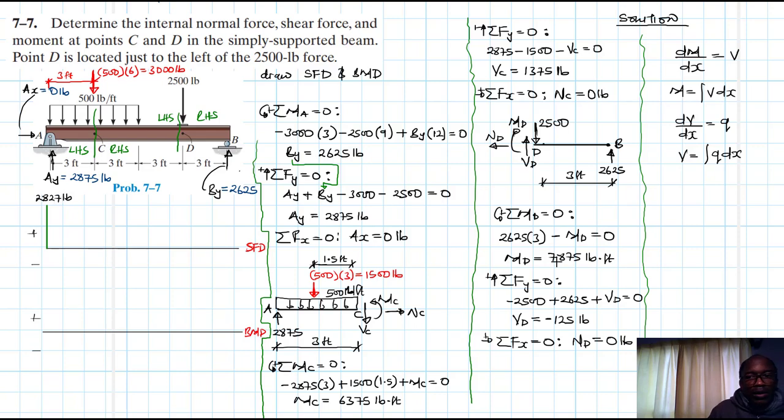All right, so what happens from A to E? This is A, B, C, D, E. Let's call this point here E. From A to E, our q is negative and constant. Therefore, we expect the slope of our shear, dV/dx, to also be negative and constant.